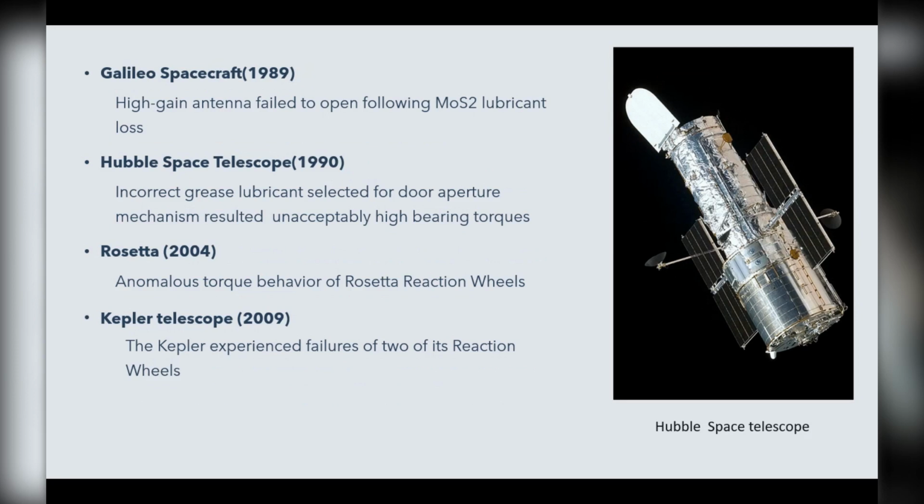But no, there were no aliens involved. The problem was actually with the metal bearings due to solar radiation whenever there are coronal mass ejections. These radiations could induce a huge magnetic field through the bearing, and it will induce arc pitting. So it will not fail completely, but it will increase the torque.